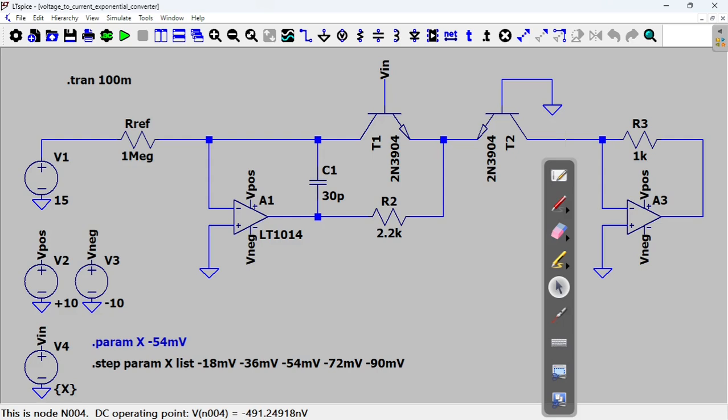And what happens is that the current is going to charge a capacitor, and that capacitor is going to discharge as soon as the voltage reaches a certain value. And this is how you can control the frequency. So the current doubles, and as a side effect, the frequency doubles. And that's how you get the voltage controlled oscillator. So the frequency depends on that V in, but it's doubling every time.